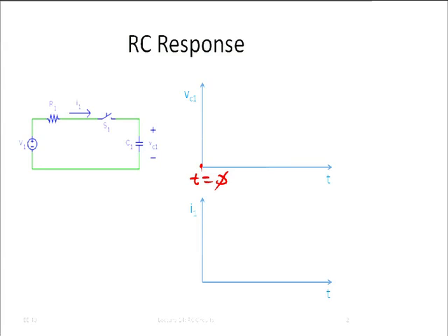But then the voltage VC1 is going to increase, and what happens to the voltage across the resistor? It will decrease, right? And consequently, the current I1 also decreases, and so we still charge the capacitor, but we charge it more and more slowly until ultimately the voltage on the capacitor reaches the value V1, and then the voltage drop across the resistor R1 is 0, right? And the current, of course, is also 0.